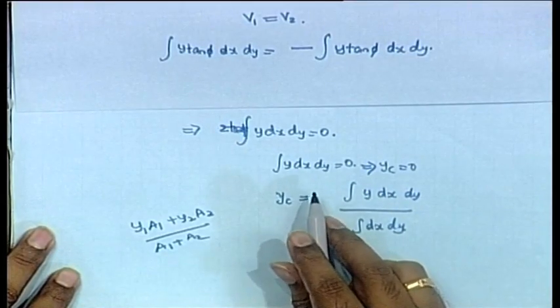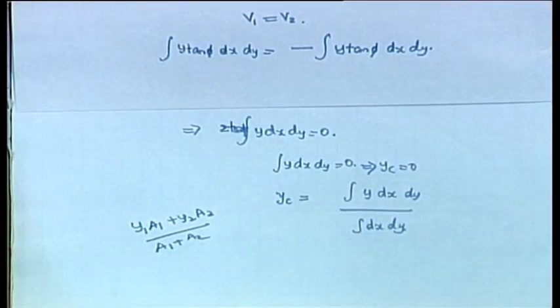What this implies is that if a system rotates in this fashion with a small angle, with two conditions: first, it is a small angle of inclination, and two, without going up or down, it just tilts slowly, such that the volume immersed is equal to the volume submerged, it will be tilting about its centroid. That is what we have proved with this derivation.